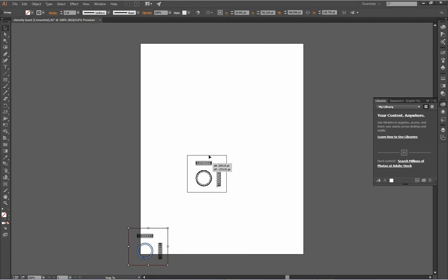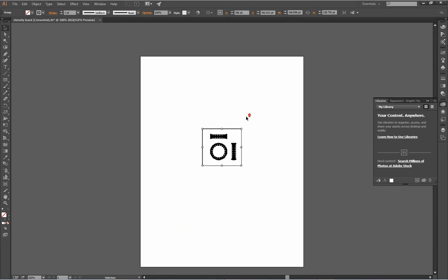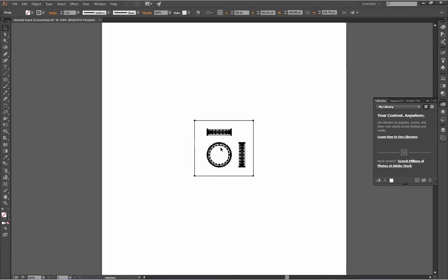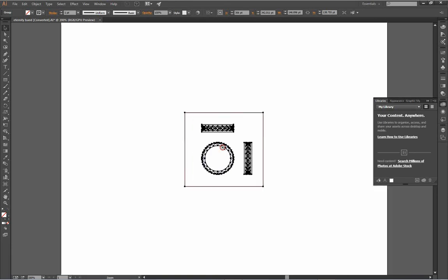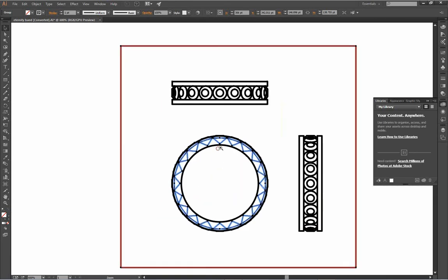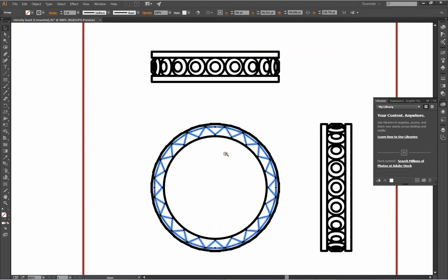Grab anywhere in here. Pull it up into the middle, and if you zoom in, it's a control space bar click, just like in Rhino. You'll notice how fat these lines are. Rhino's default line is 1 point thick. That is way too thick for what we do. If you're going to draw some more on something in Painter, I make it 0.33. If this is going to be your finished lines, which in this case, as small as this is, it would be, I'd make it 0.22.